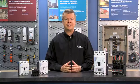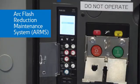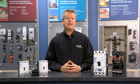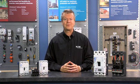The arc flash reduction maintenance system, or ARMS protection setting, allows you to quickly de-energize the circuit breaker to substantially reduce the arc flash energy, protecting your people and equipment. The applicable standards for circuit breakers are UL 1066 for power circuit breakers and UL 489 for insulated case and molded case breakers. The IEC standard for circuit breakers is IEC 60947-2.